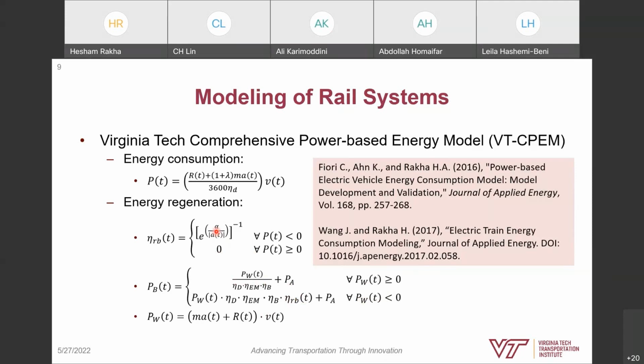And then from that, we can compute the energy that we consume every delta t. So basically, based on the power, you multiply the power by the delta t that you're computing that over. So in our case, it's every decisecond. If we multiply it by every decisecond or every second, we get the energy we consume over that second. We sum it up across all the seconds in our trip. That gives us the total energy that we consumed in our trip. We sum it up across all the vehicles. That gives us the total energy we consumed in the entire network. If we're trying to compute the energy related to a specific individual, then we divide this energy by the number of passengers on that train or that vehicle, and that gives us the contribution of that person to that energy that is consumed.